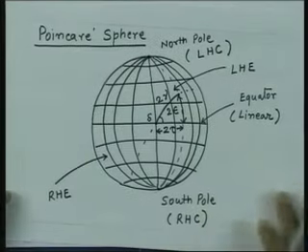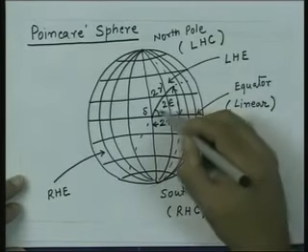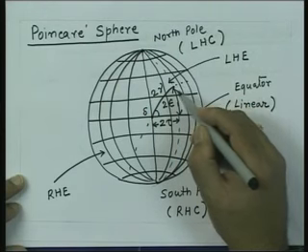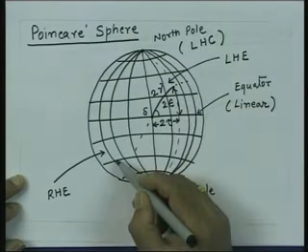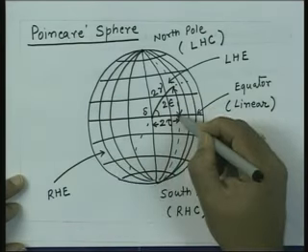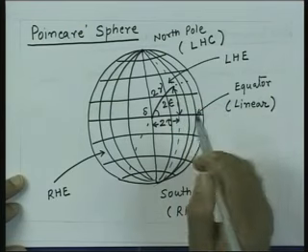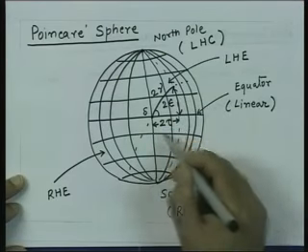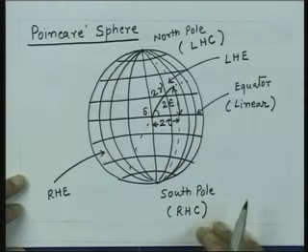What about the elliptical polarization? If I take some value here for epsilon in northern hemisphere, then the diagonally opposite point will definitely lie in the southern hemisphere. That means the axial ratio will have the same value, but the sign of that will be opposite, and this 2 tau angle would have changed by 2 tau plus 180 degrees.